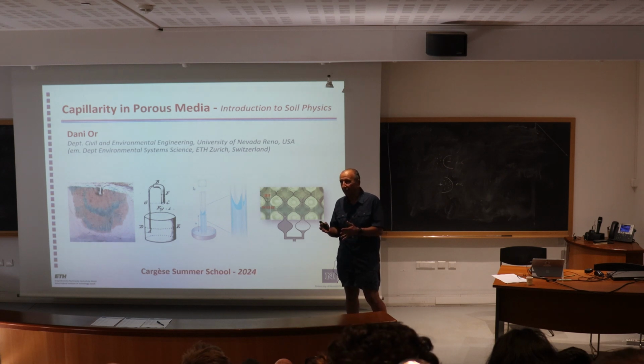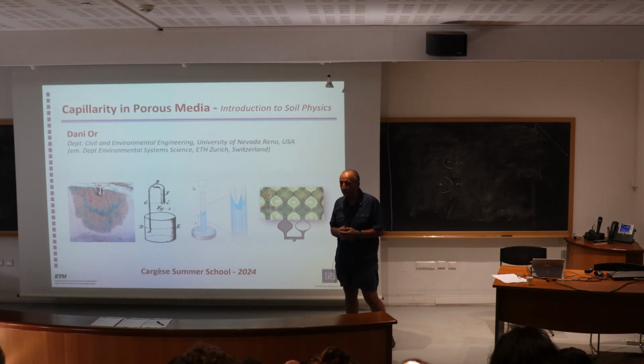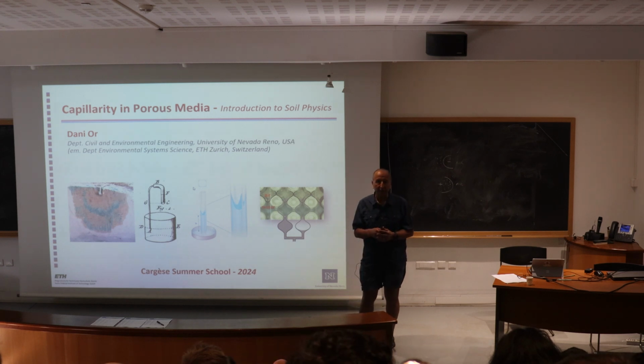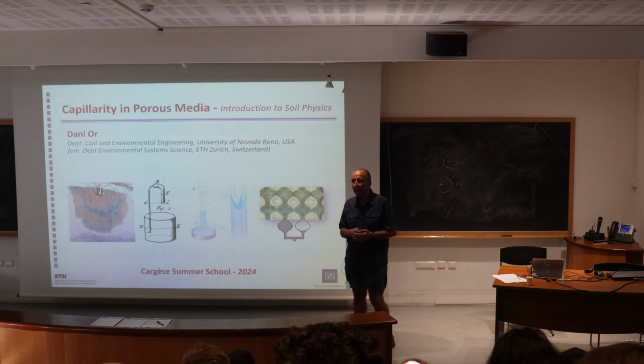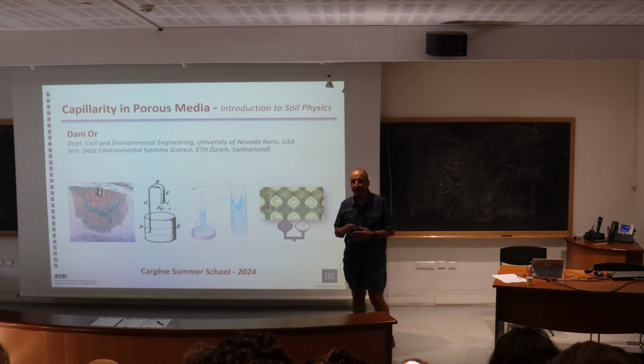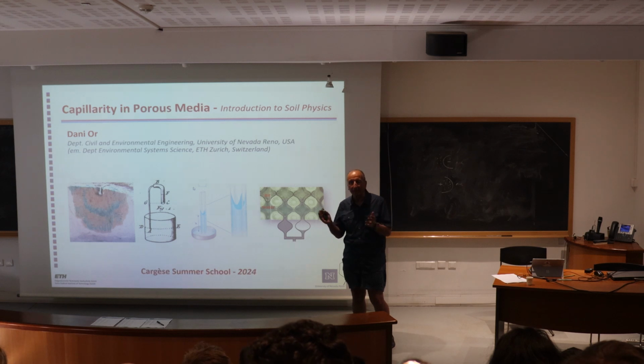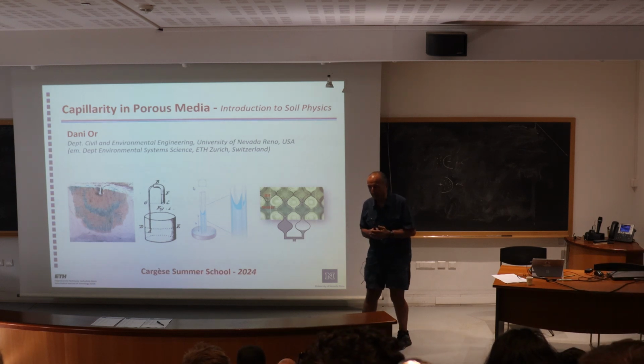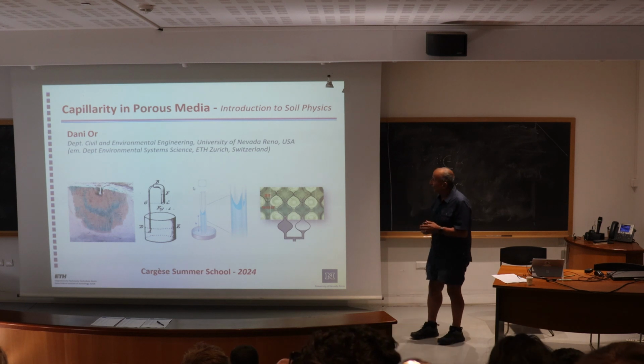In other words, if yesterday we focused on groundwater and on saturated state, here we'll be on unsaturated state, in which we have coexistence of water and gas within the porous medium, and that gives rise to a whole bunch of processes that I'll collectively call today capillary processes, but they're not only capillary processes, as you'll see later on.